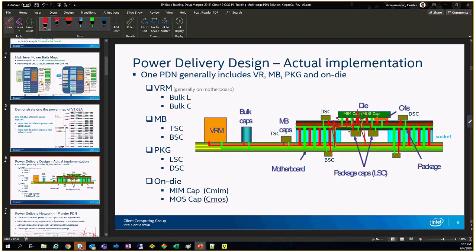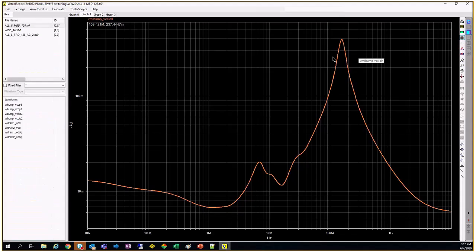By reducing this path, the path from the package base to the package top, you will bring down this impedance dramatically. You will actually see, you can bring it down. And because of the capacitor's position and the value of the capacitor which can be used, you cannot always have an effect at these frequencies. Package caps stop at this frequency. More than this, very difficult. After 20-25 megahertz, package caps will not have an effect because of where they are placed. So this is what you do in time domain.